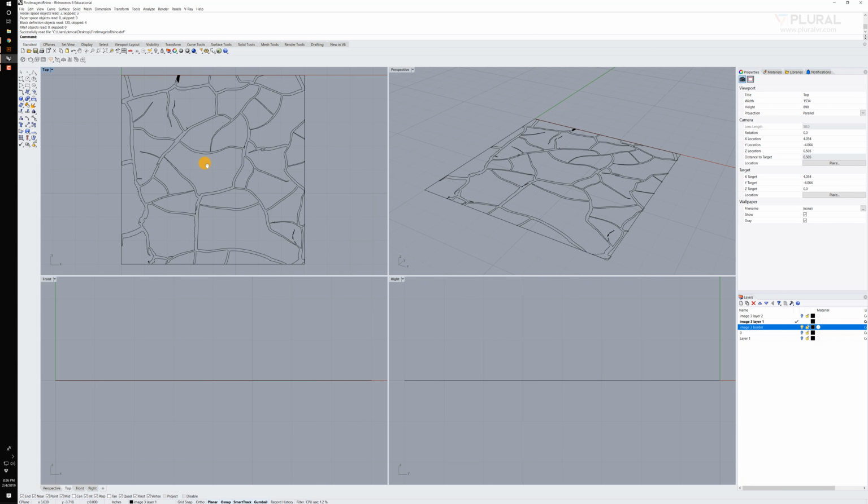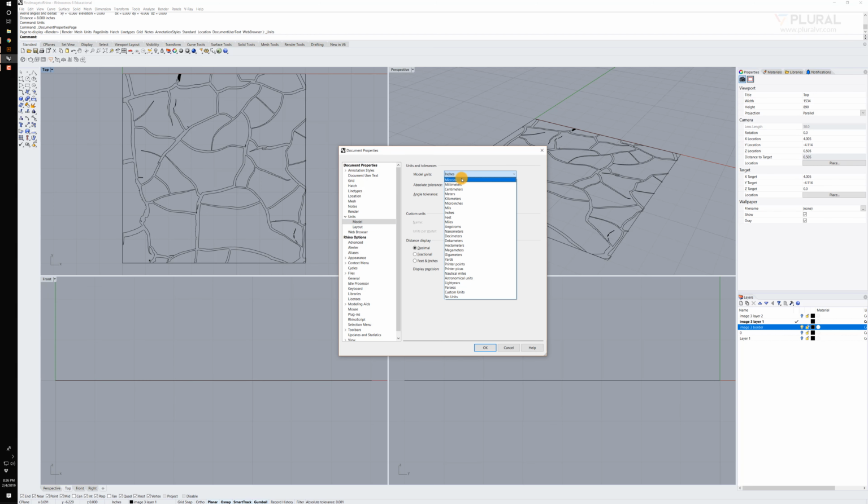at the right scale. So if I type distance, I can click on the left side and go to the right side, and you can see it's set to 8 inches. I know I've brought it in at the right scale. If for some reason here at the bottom you see that your units are not inches, you need to change them. And we can do that by typing units. In units here I can change my units by selecting feet, inches, millimeters, whatever it needs to be.